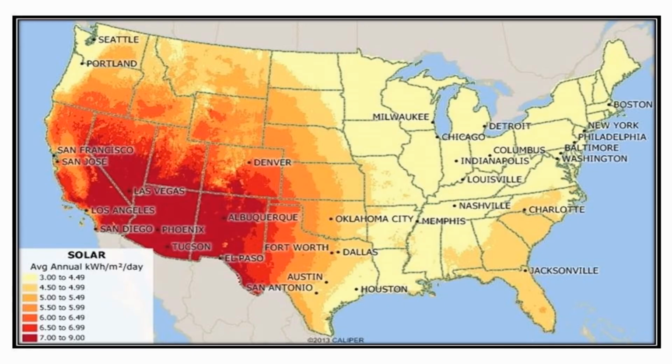You recall this map from before showing that the eastern half of the United States is capable of solar generation at 1/2 the rates as the western half. Therefore, the same 550 megawatt solar plant used in the west only generates 225 megawatts when used in the east. So twice the amount of real estate is required to produce the same 550 megawatt output.